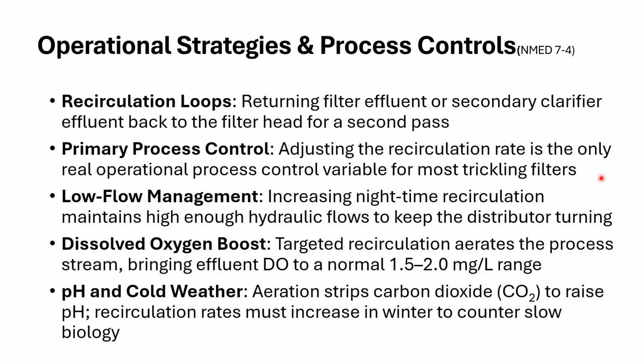And when you think about it, you're going to get a couple of different questions on your exam, maybe one or two, but it's well worth thinking about. For a trickling filter, the only variable you can control is the recirc rate. So you can increase it or decrease it. Think about what you're trying to do, and that'll give you the response you want: an increase in recirculation rate for the trickling filter or a decrease. Think about that as you go through some of the homework problems and some of the exam problems. But that's about the only thing you can control in the trickling filter.